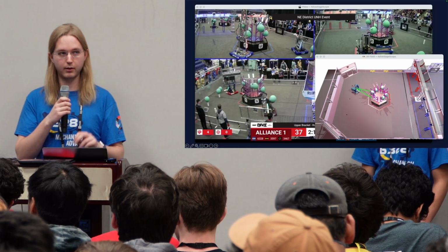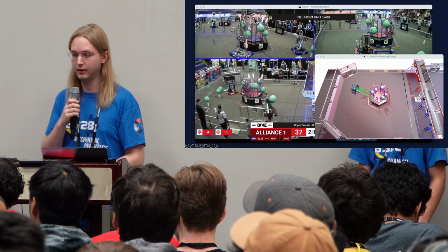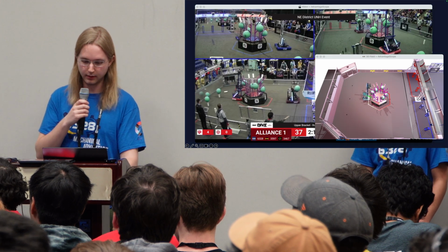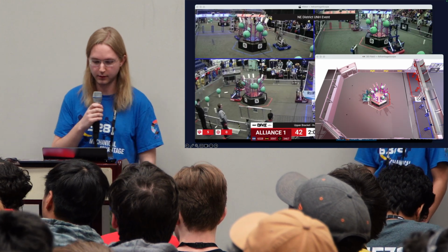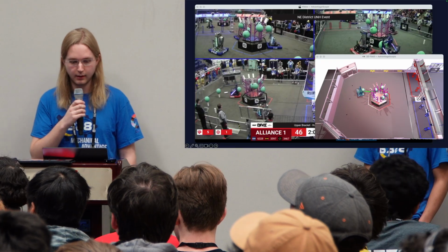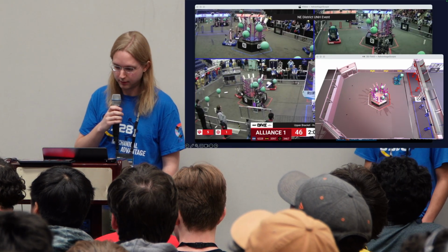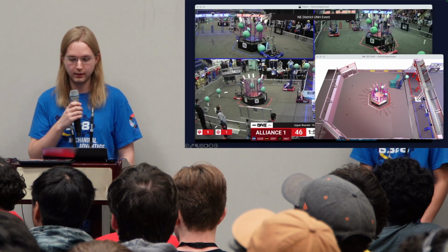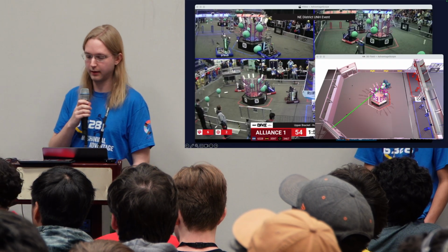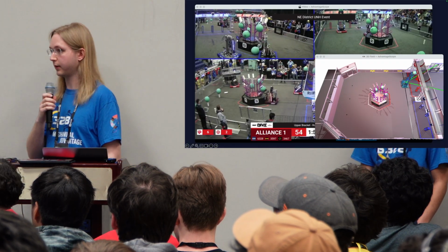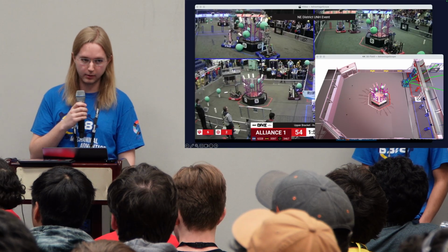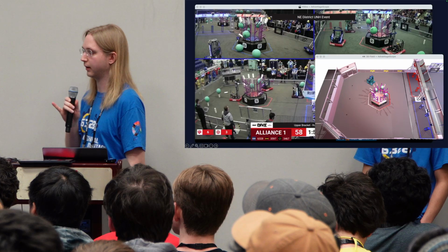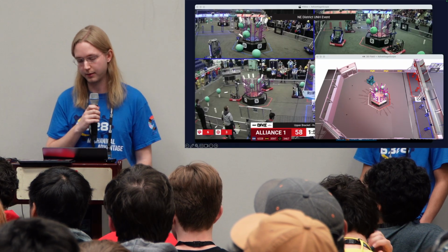This is how the robot would have calculated its position if we had been running this new and improved tuning during the match. So the accuracy, you'll see, is similar as we're swerving across the field in a moment. But as we arrive at the net, you'll see that the replayed pose jumps more quickly towards the vision estimate, so it's more accurate. We can see we're improving our accuracy without significantly worsening our noise, which is what we like to see.